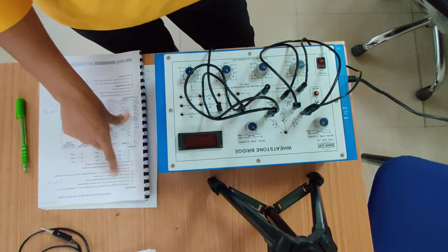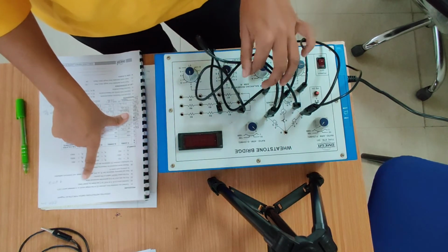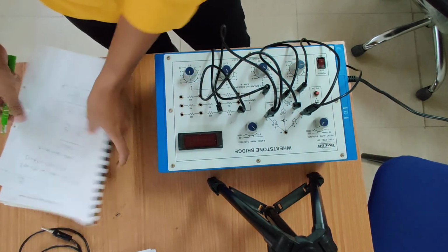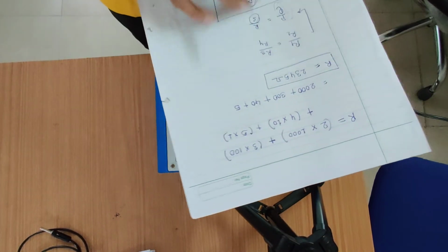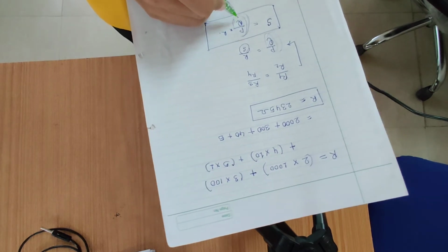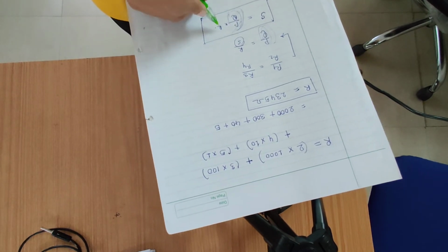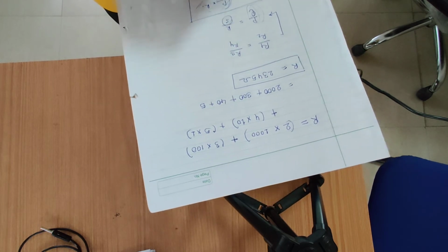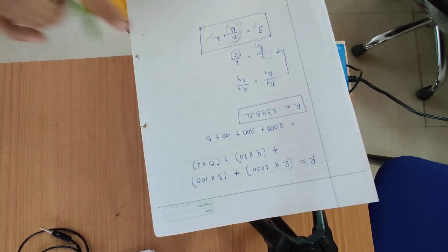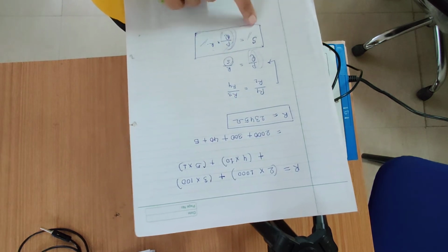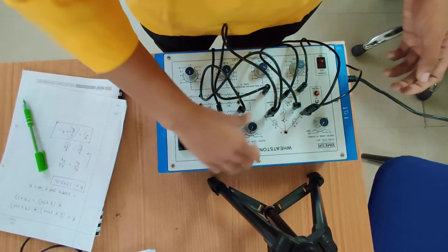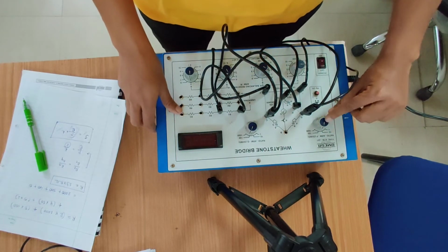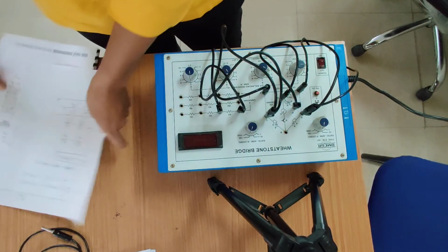Now put the ratio arm PQ at appropriate resistance value. Look, in the equation we have P divided by Q. I will simplify this. If these two values are equal, then I can simply cancel them and whatever value of R I get would be the value of unknown resistance S. So I need not do any calculations to find the value of unknown resistance S if I have the same value for P and Q. So let me take both values at 100. Let P be 100 and Q also at the 100 position.